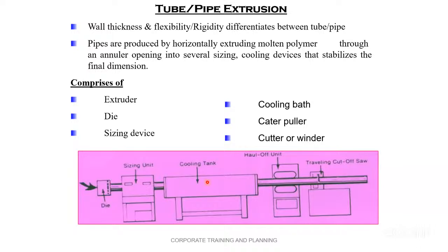And hence, you require a higher length for PP and HDPE as compared to PVC. PVC, I told you, cools very fast, heats very fast. But polypropylene or polyethylene takes more time to cool and more time to heat. You have seen while designing the screw also.